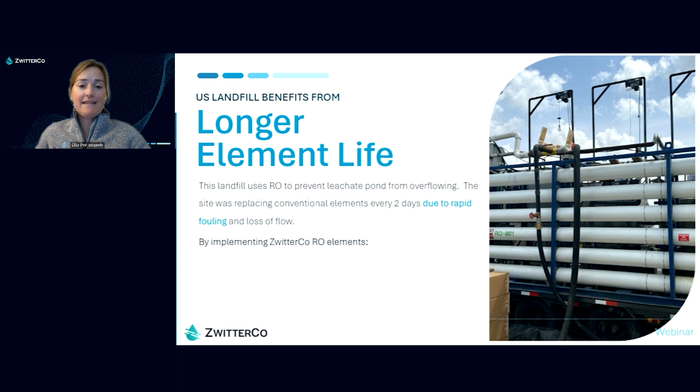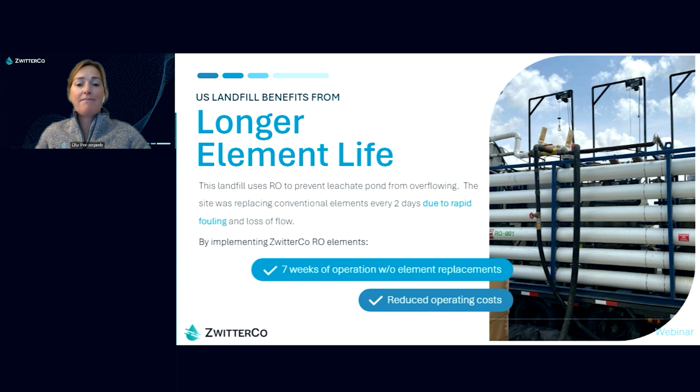By implementing ZwitterCo RO elements and by making a few operational modifications, the site saw some immediate benefits. They were able to run for 7 weeks without any element replacements. And due to less fouling, more stable operation, and less frequent element replacements, the site was able to significantly reduce their operating costs and are looking to install ZwitterCo RO elements in other leachate treatment systems at other landfills.